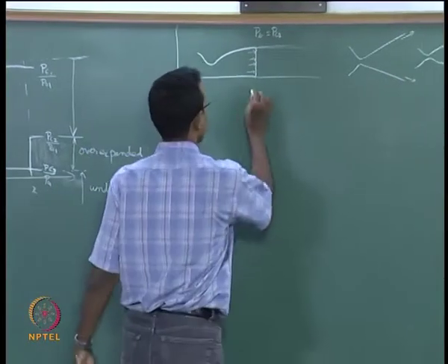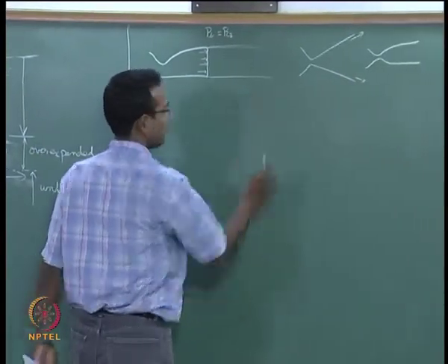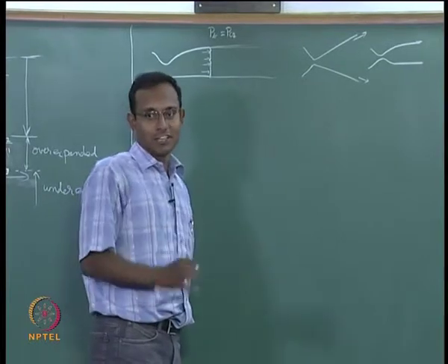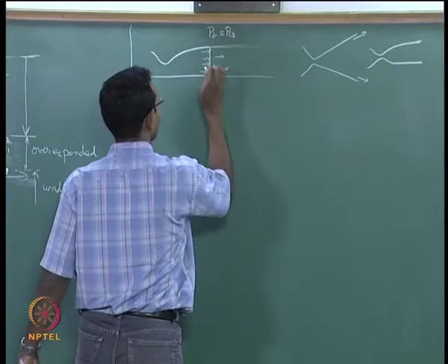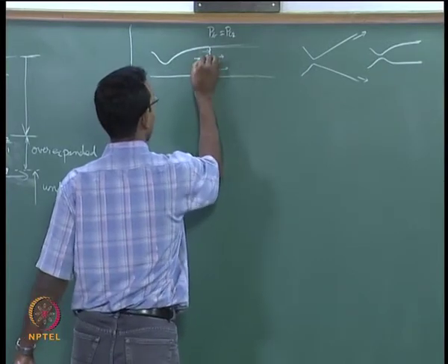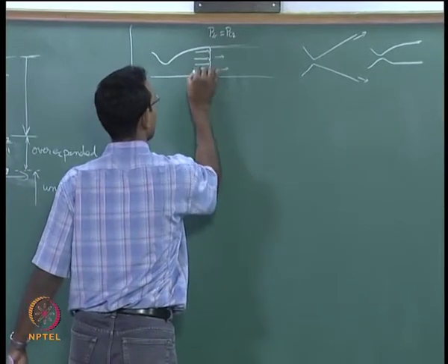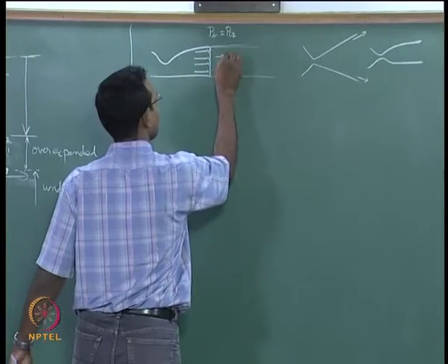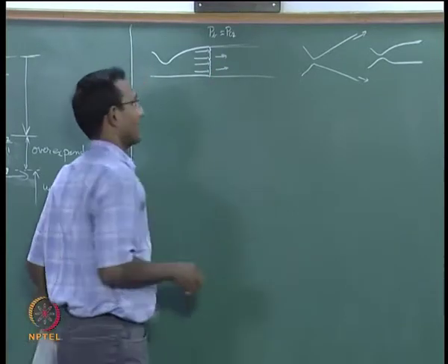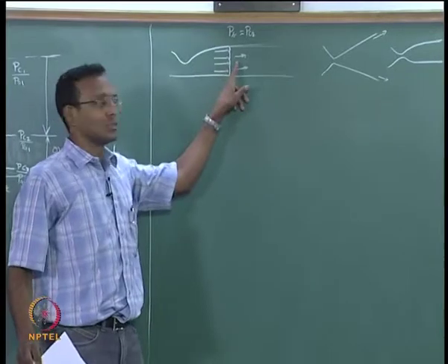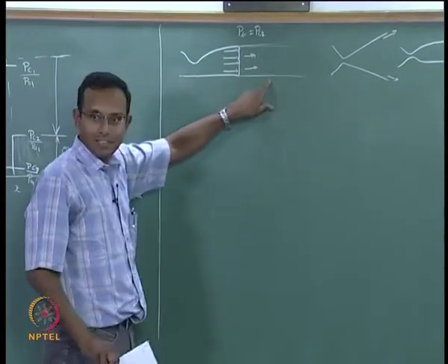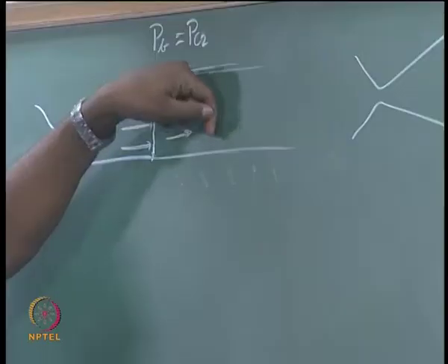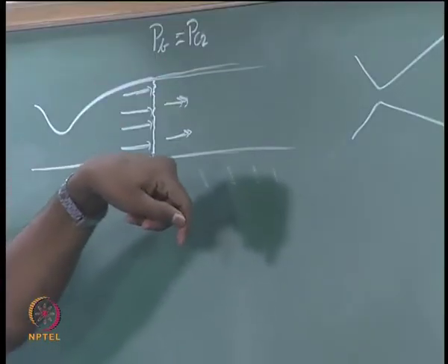Okay. So, there is outside air and it is stationary and this gas is going with some reasonably high velocity. I have to draw arrows such that these are longer and these are shorter. Okay, we know high speed flow becomes low speed flow here. Okay, and the pressures are matching exactly. So, no fluid element is going to push the next fluid element, right?